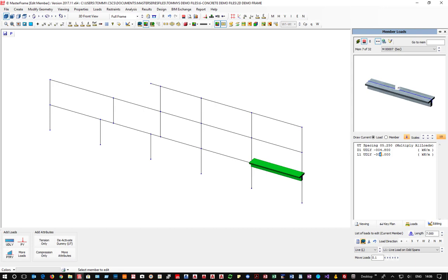Well, if you take that previously done point load, let's say I want to put a point load onto this member, and this one, well, it's pattern loading, so we're going to say that one and that one, that one and that one, and then those two as well, but with a different load factor. So what I would do is I would go to copy mode.